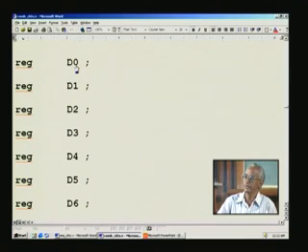Earlier we have used D0 through D6 in an always block, if you remember, and therefore they are declared as reg here. So this is a mandatory thing, you have to declare any signal that you use either as a wire or reg, and even outputs would be normally a reg if it is coming from the sequential circuit.